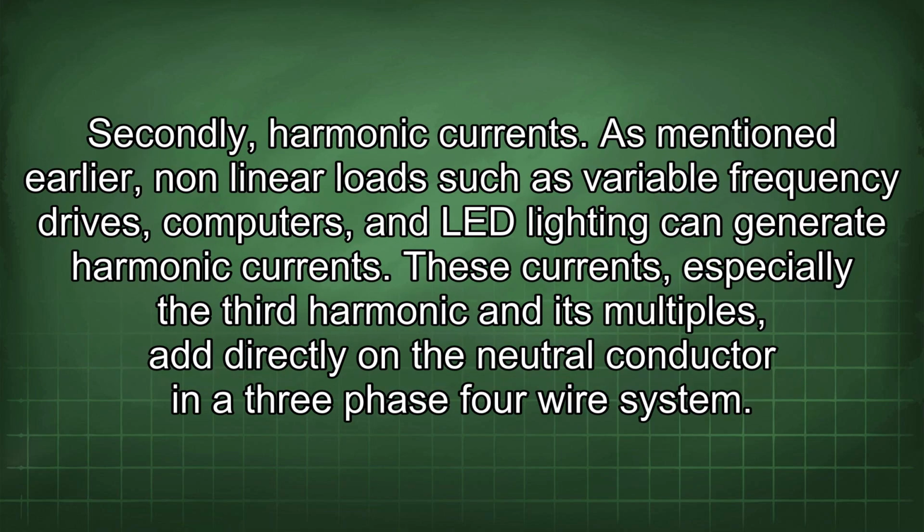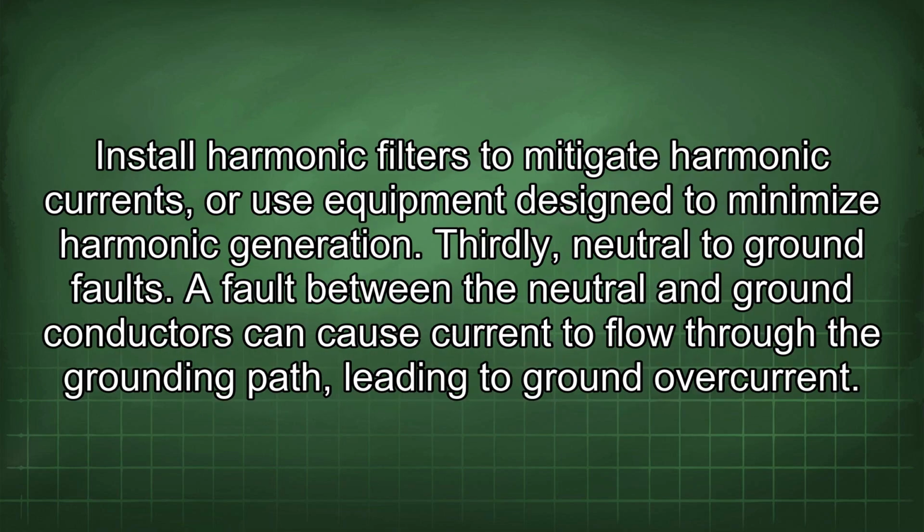Secondly, harmonic currents. As mentioned earlier, nonlinear loads such as variable frequency drives, computers, and LED lighting can generate harmonic currents. These currents, especially the third harmonic and its multiples, act directly on the neutral conductor in a three-phase four-wire system. Install harmonic filters to mitigate harmonic currents, or use equipment designed to minimize harmonic generation.